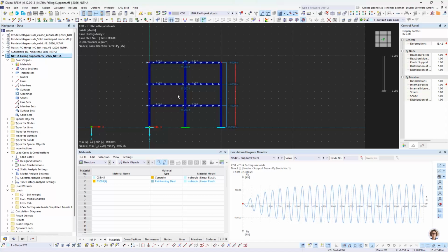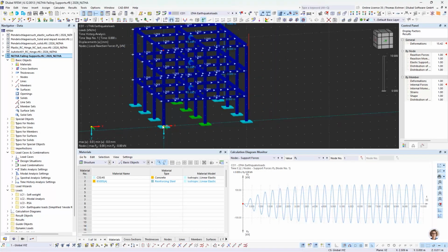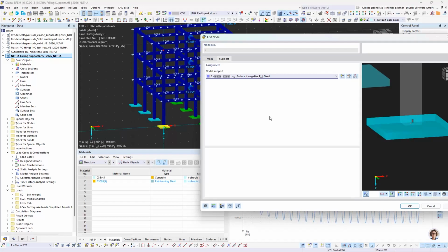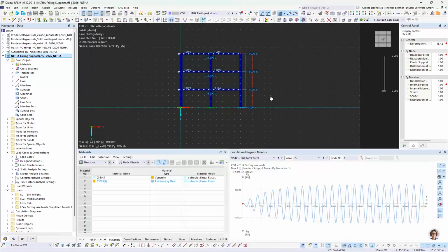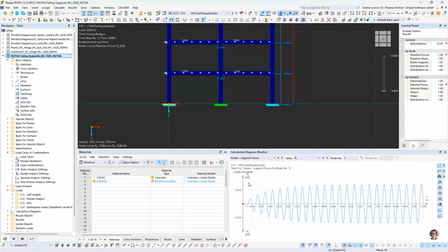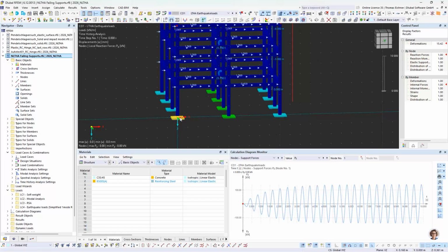And that's gonna be some failing supports. Here you can see I just prepared a model which has fixed supports, but it has failing supports if the force is pulling up. So if this P set is negative, then the support fails. Quite straightforward here, and we already see the results of the linear time history with the results of the support force at this left corner here.